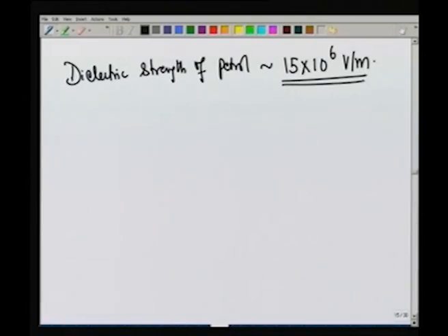So now we are really into something, because not only has the voltage dropped, the dielectric strength has also dropped. Therefore, the gap in the spark plug has to be considerably smaller. So I have given you all the numbers. You can actually estimate what the gap should be. The gap will turn out to be a fraction of a millimeter. Instead of the 3 millimeter that we got, it will turn out to be close to 0.3 millimeter, and that indeed